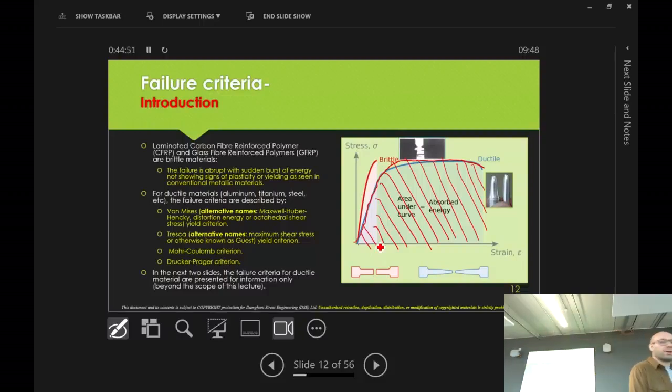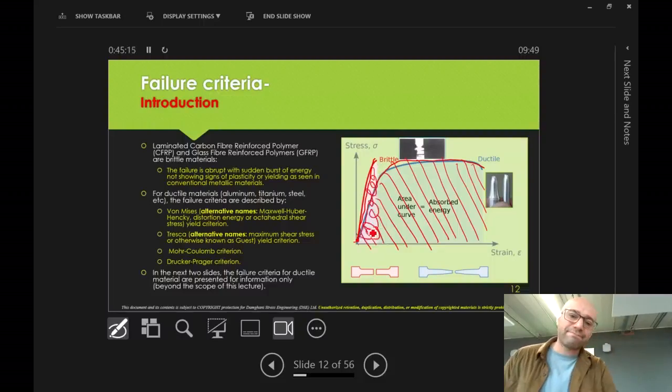The energy absorbed. So the higher the surface, the higher the energy absorption of the material. In the case of metallic materials, you see, it's a lot of energy absorption, which is good. That's what you like. But when it comes to composites, it's brittle, which means it just linearly goes up and breaks. Bang, gone. And the surface area, if you look at that, so composites are not that good when compared to metallics, is it? It's not just about strength and being light, right? Its energy absorption is poor, let's put it this way.